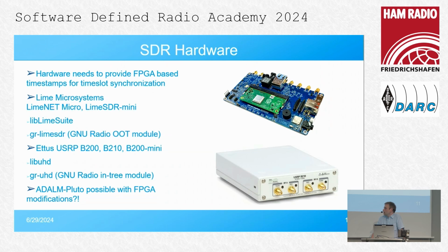About the software-defined radio hardware, first of all, I would like to say that not all hardware can be used for this purpose because it needs to provide some FPGA-based timestamps in order to do the time slot synchronization, so time division multiplex access requires that.